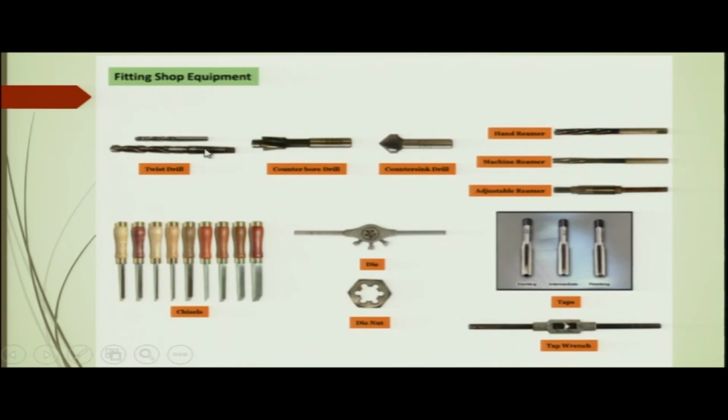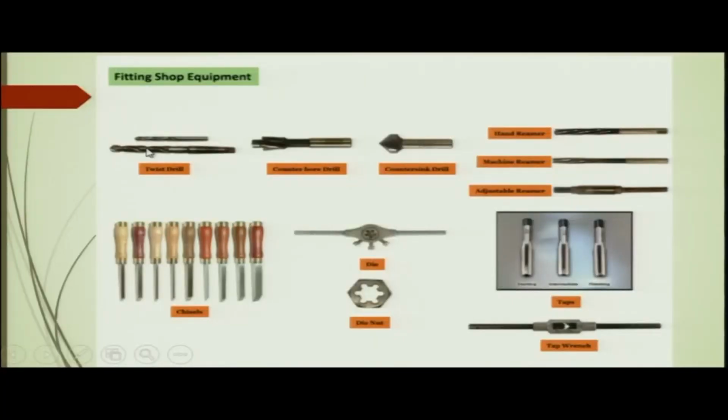So, when this drill goes in, the internal Morse taper of the drill holder holds this drill through the external taper that the drill has. That is it. There is nothing else in between this shank and the holder. There is no screw which needs to be tightened. The torque transmitted from the chuck to the drill is only through the friction between the Morse tapers, that is the external taper of the drill and the internal taper of the drill holder or the drill chuck.